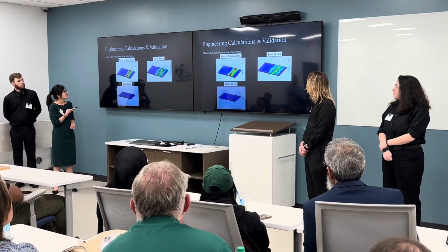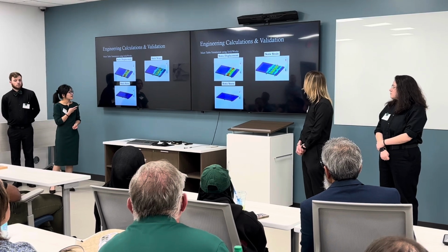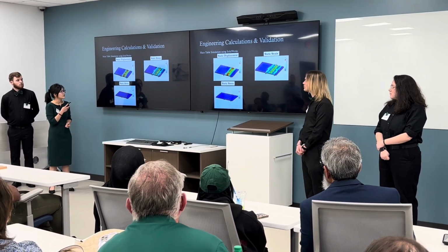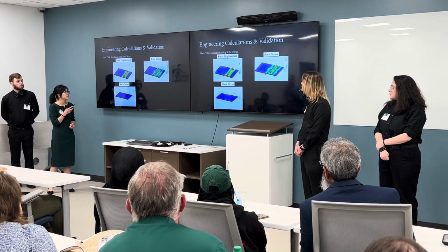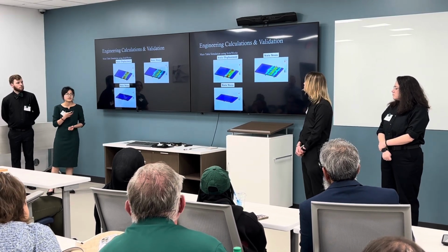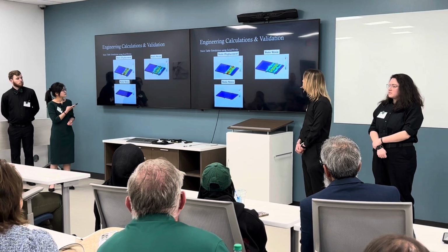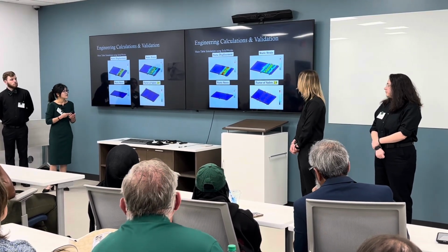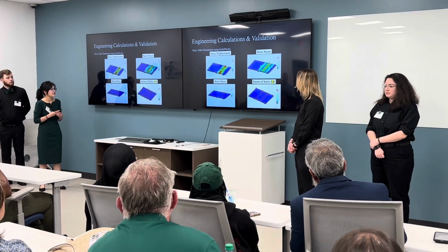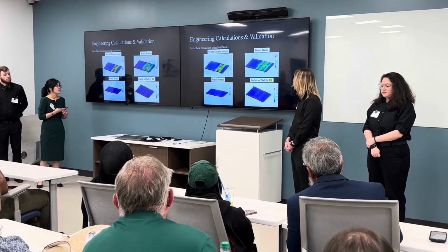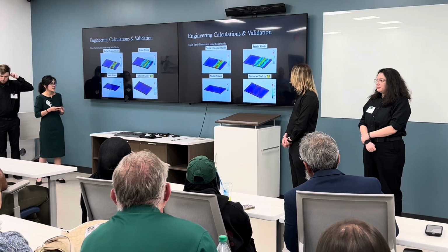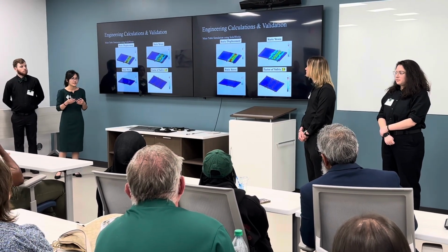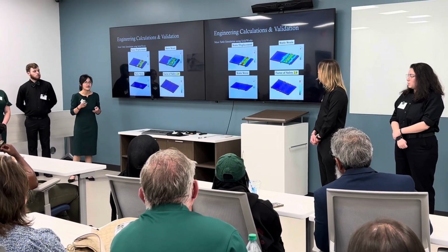The strain and stretch that we show right here is green to blue, which is really safe to handle that stress and strain. And the fourth one is the factor of safety for the main table. It's 2, so that means it can handle about twice the stress that I applied.